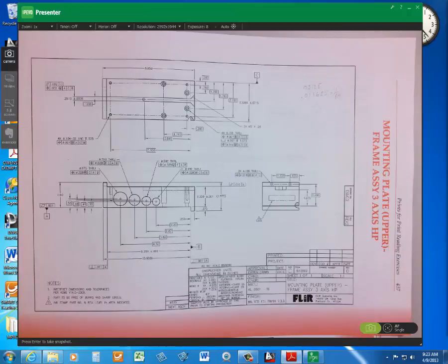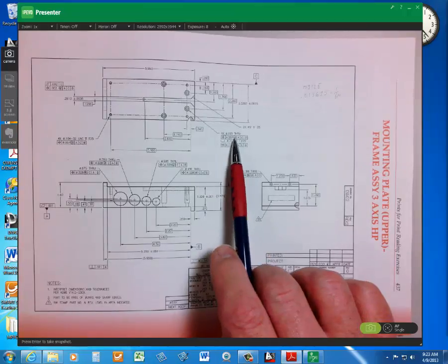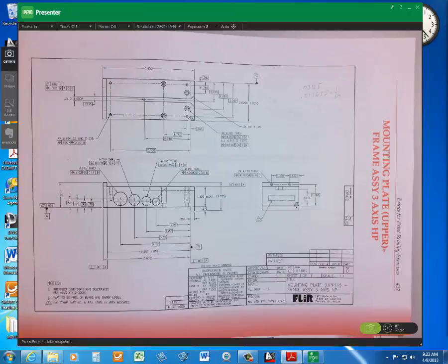there's no math required. Exactly. It's not a trick question or anything. No math. Positional tolerance at MMC is 7/1000, circle M. So as soon as you see the circle M, you know what your position tolerance is going to be at maximum material condition. It's next to it. That calculates it automatically.